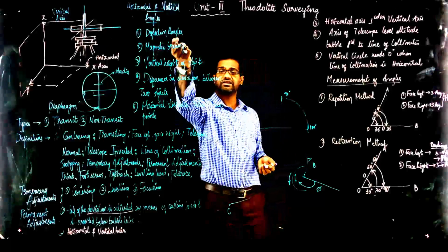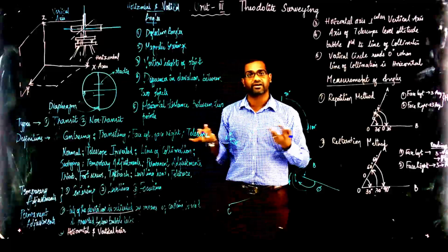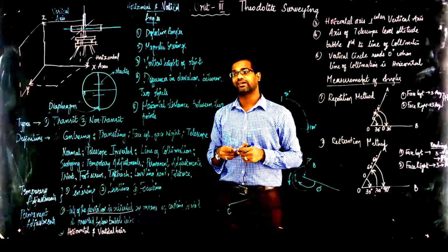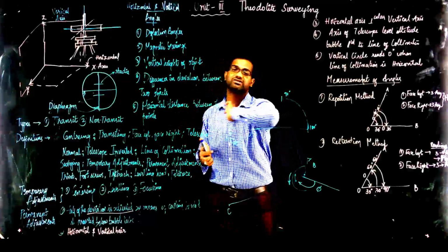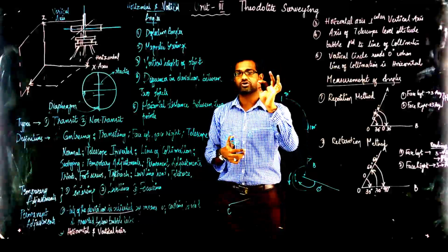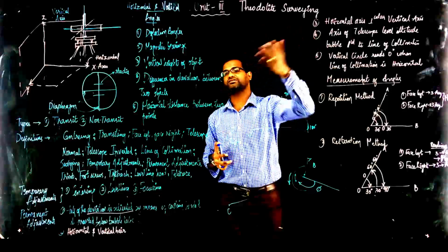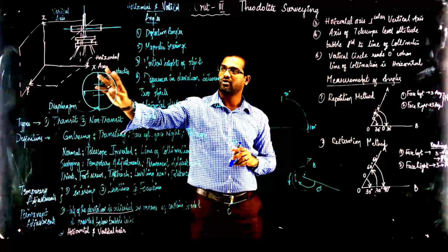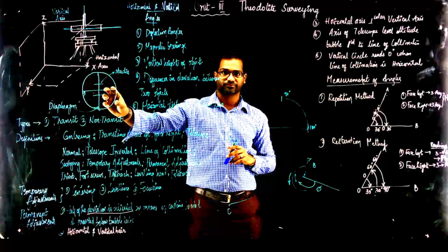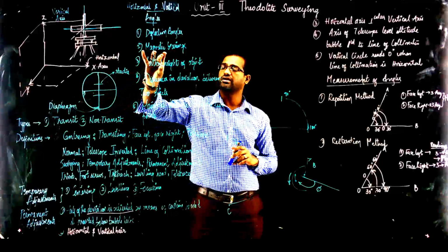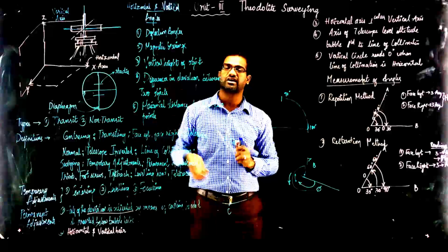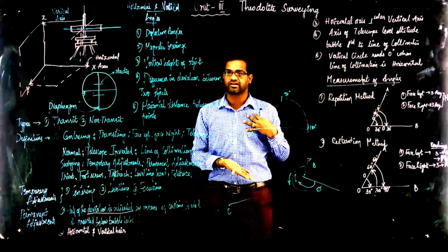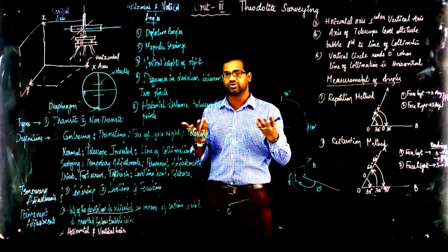That angle can be easily calculated. If you know the north symbol, magnetic bearings will also be very easy. Using trigonometrical principles, you can calculate the vertical height and horizontal distance of any point without using a tape. How far is the distance? All you need is the theodolite with the stadia and the diaphragm. Then you can calculate the vertical distance of the object, the horizontal distance from where I am standing, and the difference in elevation between two objects, also using the theodolite.